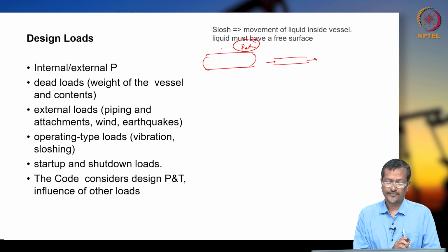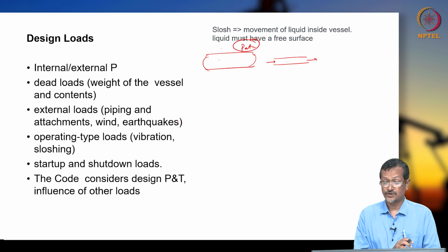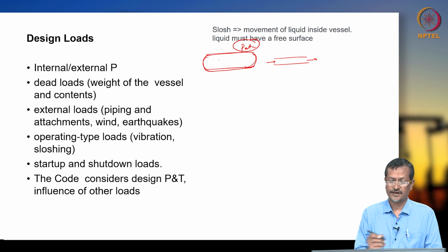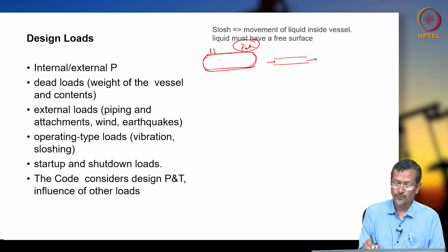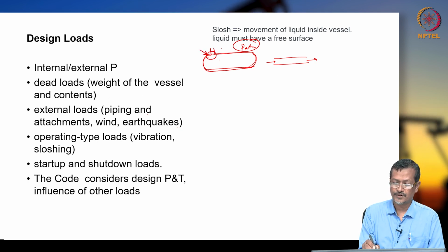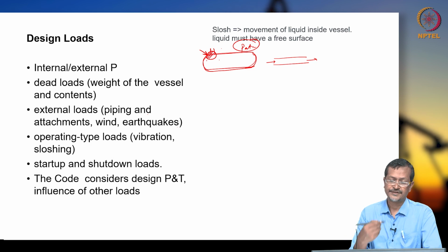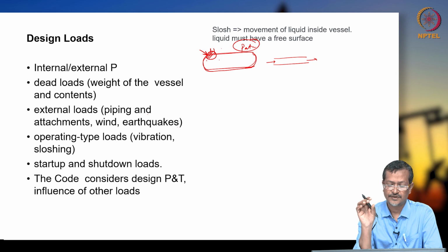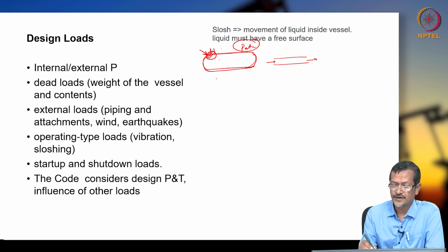Piping and fittings will be there. So fittings and attachments are also very important, because a normal separator system without fittings is fine. But when there is any fitting, the weakest point will be here. Okay, the weakest point will be the joints. So whenever you are designing any mechanical system, normally the design should start from the weakest point. The weakest point will be like joints.